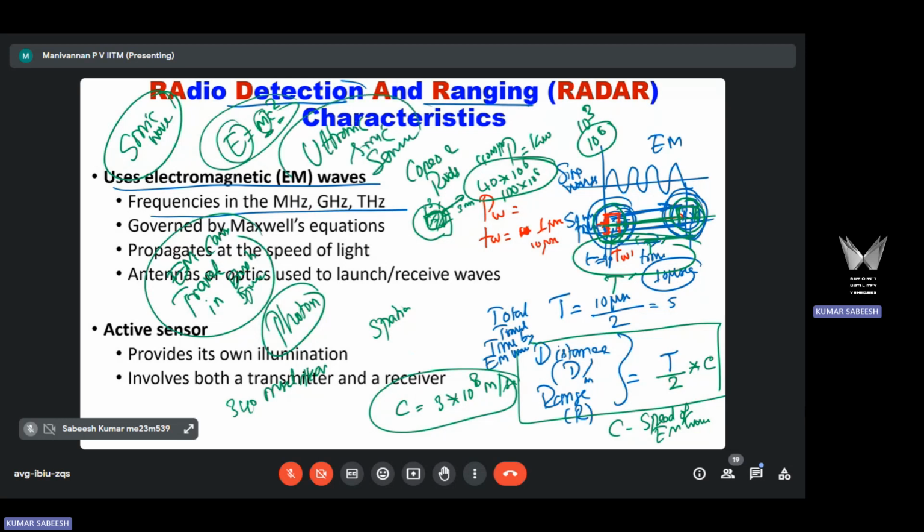We are going to see that, correct? That's also used for measuring short distances. For reversing your car, you put some 5 sensors on the backside. They are ultrasonic sensors, and they work on the same principle. Instead of sending a light wave, we are transmitting sound waves using the ultrasonic sensor. It generates sound waves. The only thing is the frequency of the sound is above 20 kilohertz.